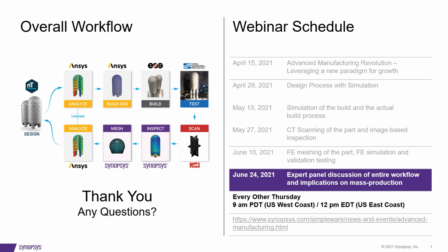What's important to know is that in the simulation, we fixed the 4 legs at the bottom completely, and in a way that was overkill, but it simplified the simulation time for static simulation, as you can imagine. But it also creates a situation where you create additional stresses, and so from that point of view, there might be ways you can do the simulation slightly differently, or make modifications that allow you to have more of an apples-to-apples comparison with the experimental results.